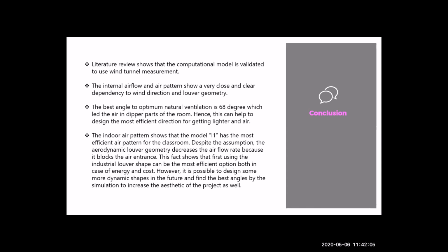First of all, the literature review shows that the computational model is validated using wind tunnel measurement. Second, the internal airflow and air patterns show a very close and clear dependency on wind direction and louver geometry. Third, the best angle for optimum natural ventilation is 68°, which leaves the air in the deeper parts of the room. Hence, this can help to design the most efficient direction for getting lighter air.